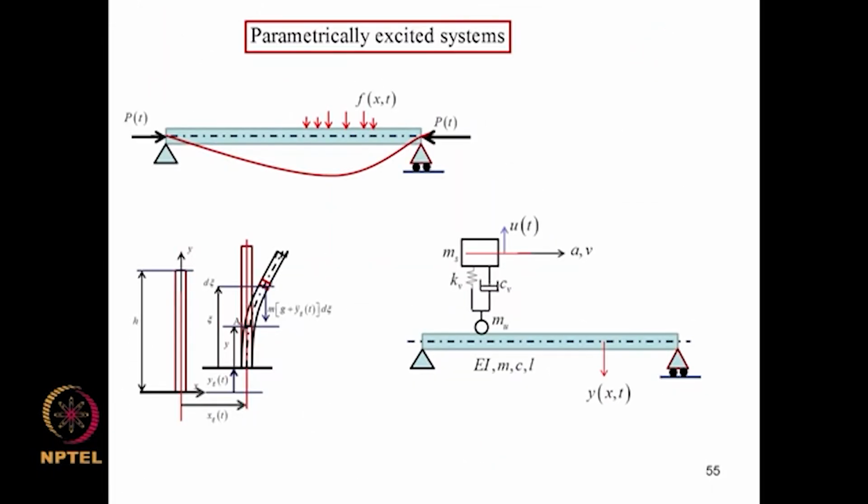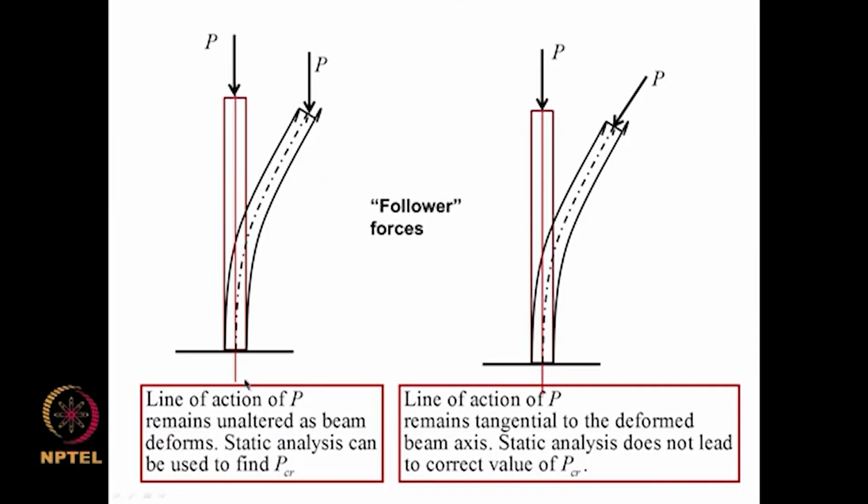We considered subsequently another class of problems where the axial loads were time varying. We considered 2 situations: a tall stack under biaxial earthquake ground motion and a bridge structure which is traversed by a vehicle. We formulated equations for these 2 systems and showed that the coefficients in the governing partial differential equations are time dependent. So such systems are known as parametrically excited systems.